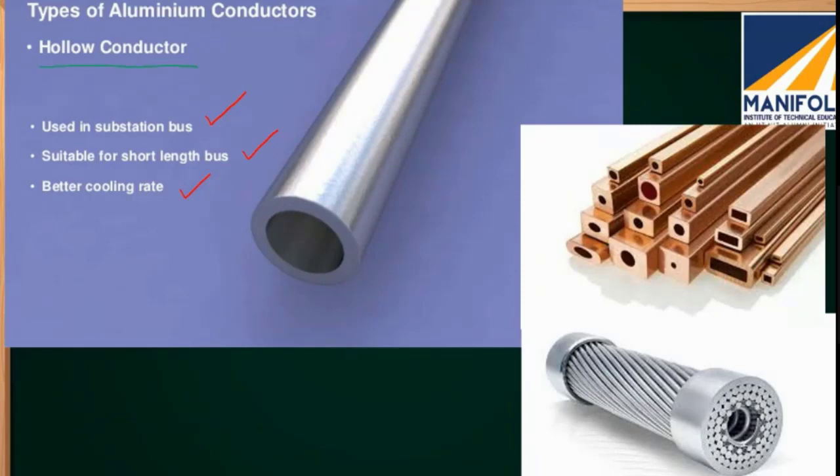And the second point is, to the same bus bar, you are connecting the generator and you are also connecting the transformer. Connection is not simple. You have to bolt the copper conductors with lugs, bolts, washers, and nuts. So the bus bar should have more physical strength, more tensile strength. That is one requirement because all bolts and nuts will be connected to that.